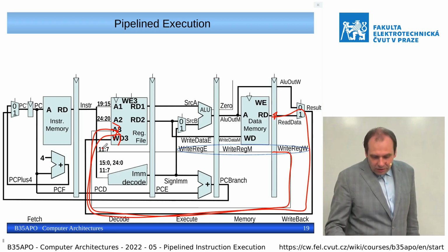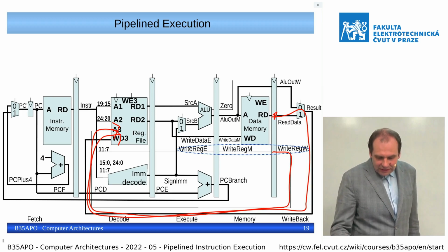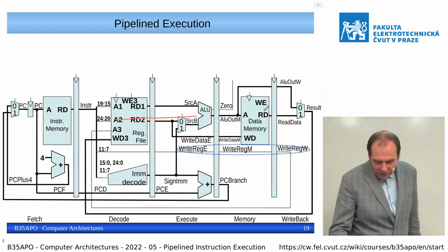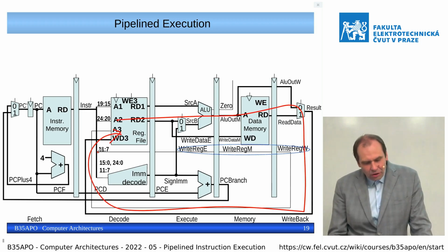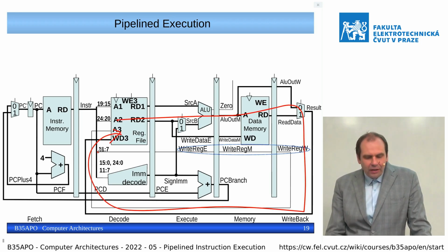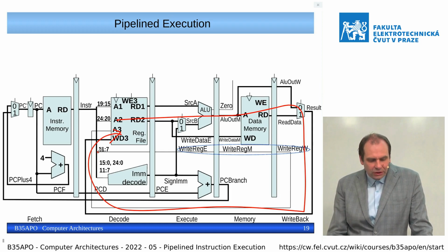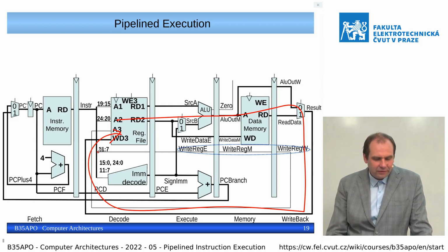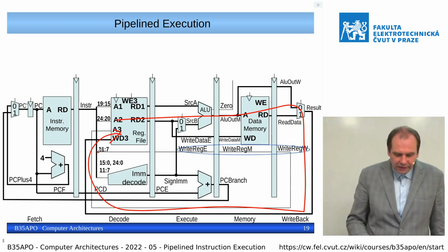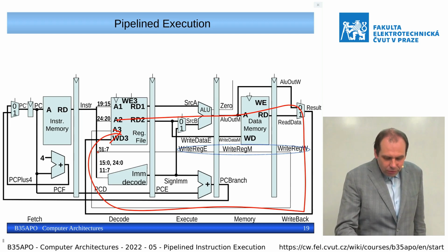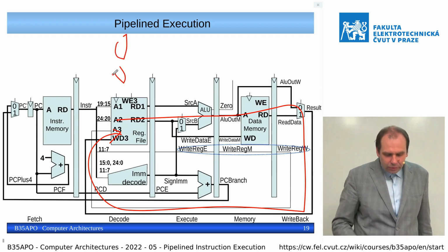Okay, so in this case, we see that it takes 3 clock cycles before the value is modified and stored back to the register file. For sure, if we have 2 instructions in our pipeline design, which is a scalar, so it doesn't allow processing multiple instructions in parallel, we are sure that 2 instructions are not in the decode stage together.